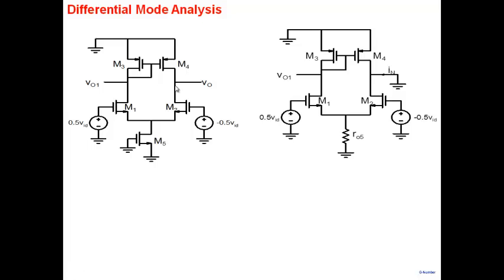And that involves two things. One is to calculate Norton's current. So you take that particular node, short it, and calculate the current that goes into that particular node. And in this case, the analysis is exactly the same as the bipolar here.